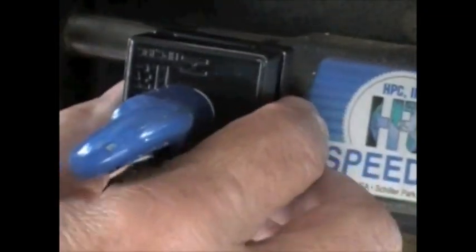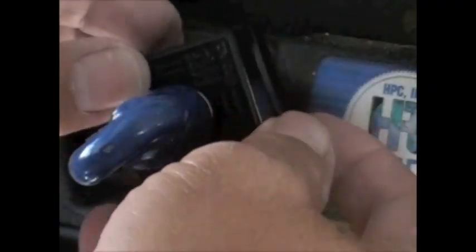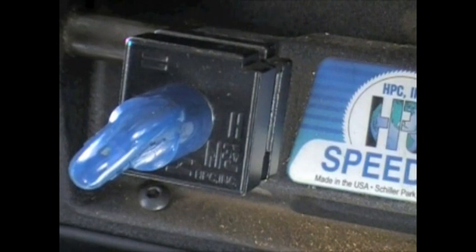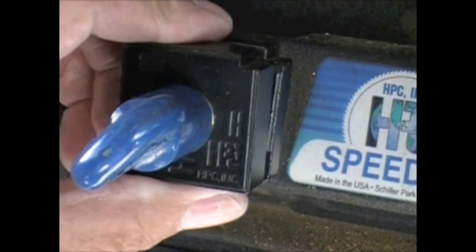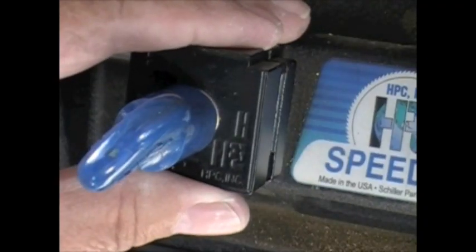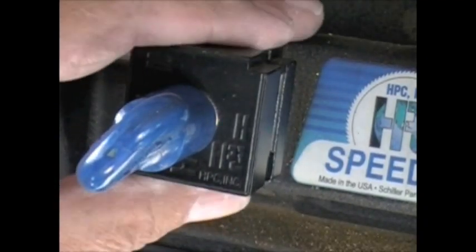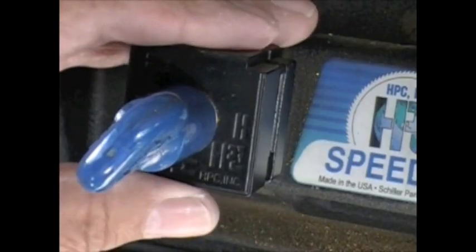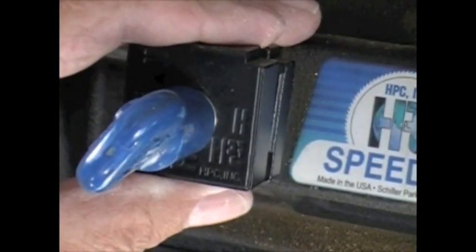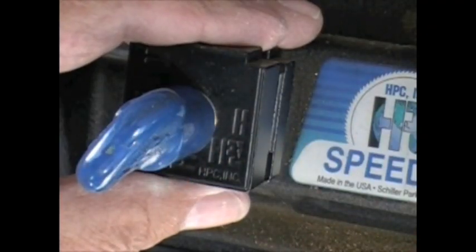So they have, again, four different sides, depending on if the key has an unusual cut to the bottom edge of the key as to which way you would set it. So whatever key machine you get, you want to study the manual to see what it says about the jaws and how to turn the jaws. Obviously, you would turn both jaws, not just the one. You want them both set the same normally.